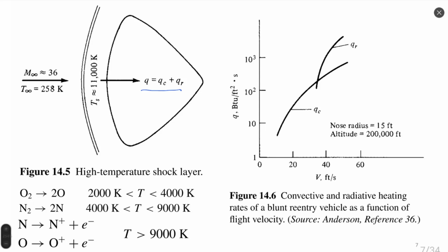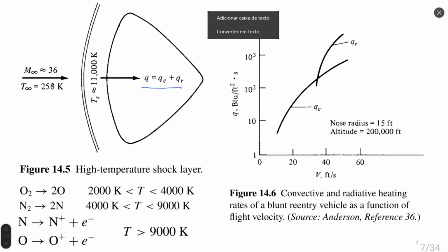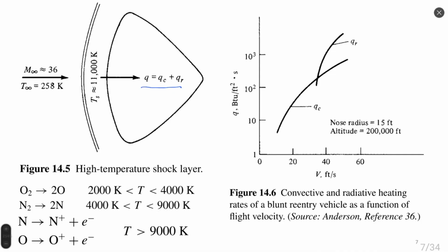On the lower part of slide 7, we see chemical processes, or chemical reactions. They are reactions of decomposition, and they are reactions of ionization, dissociation and ionization of chemical species. Since most of the re-entry processes which we must take into account happen inside air, we have to see dissociation, recombination, or ionization of air and its components.